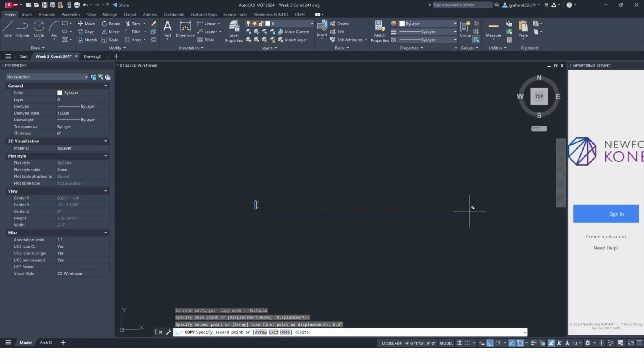And the way that this works is a little different than Revit. In Revit, you could just keep typing 8.5, 8.5, 8.5, and it would keep adding from your last place. This one, we can type in 8.5, but for the next place we'd actually have to type in 17 inches, because we're moving it. So in order to get it in the next spot, I believe you'd have to type in 17 inches, and that would put it there. So is that something I want to do every time, keep adding numbers to it? No, right?